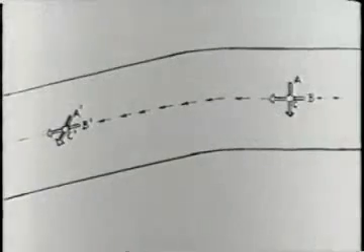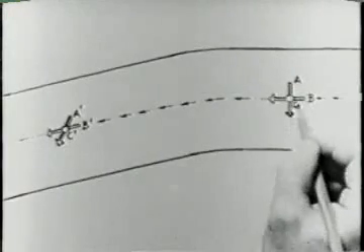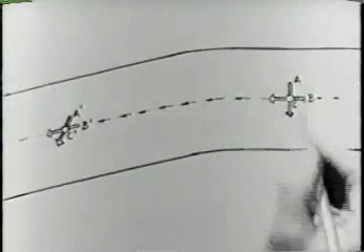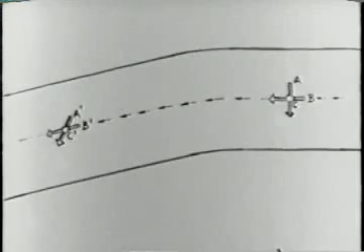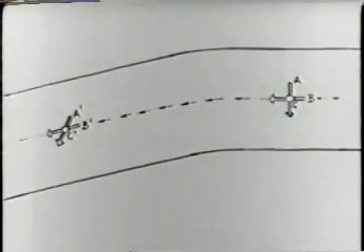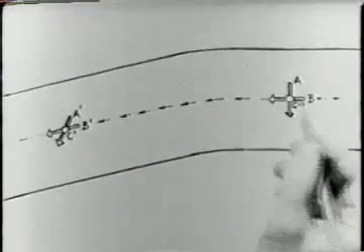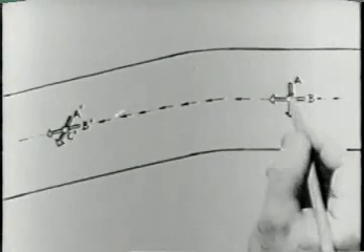Now I am putting in the little streamwise vorticity meter at the end of the bend. Somehow, a streamwise component of vorticity has been generated in the bend. To see why, let's look at three perpendicular fluid lines, A, B, and C, in the upstream position. If we neglect viscous forces compared with inertial forces in the bend, we may imagine the vortex lines to be frozen to these three fluid lines.